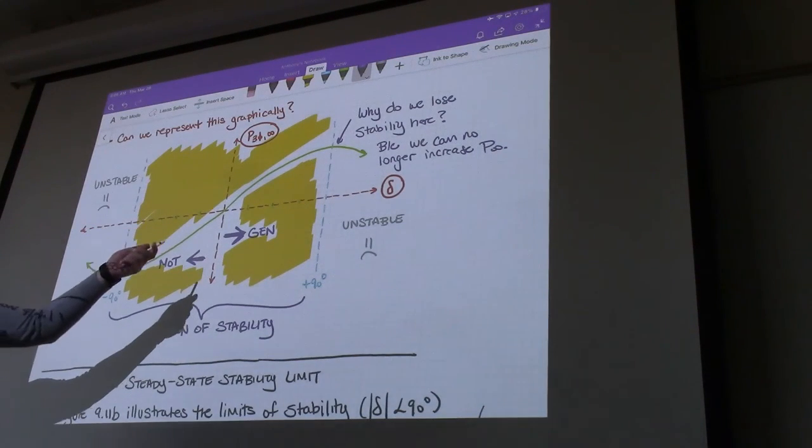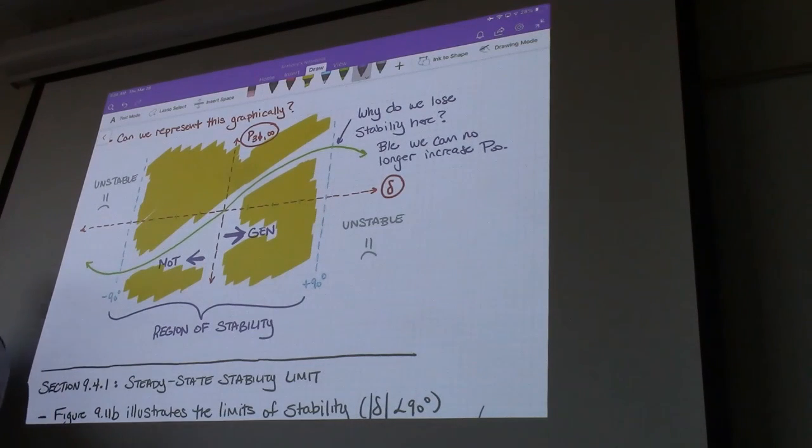So that's essentially what's happening right here: the instability is because you've reached the maximum of what, for this given condition, meaning that you're not playing around with the IF value, that generator can put out. And so the more you push the gas pedal, you're only making the situation worse by making the difference between the generated power and the required load wider and wider, making that gap even wider.